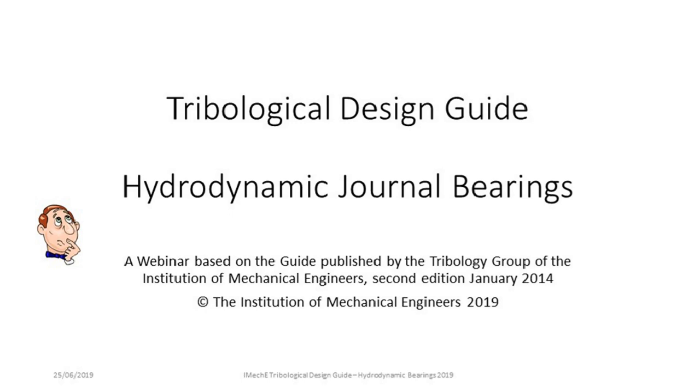Well, interestingly, with an electric motor, it's always a good idea to match the characteristics of the bearing to the characteristics of the device into which you're fitting the bearing. Now, the point about electric motors is they produce very high torque at very low speed, which is why they're attractive for vehicles, of course. But that means they're not very attractive for hydrodynamic bearings, because hydrodynamic bearings have no load capacity at zero speed. So electric motors tend to use rolling element bearings, and transmissions invariably use rolling element bearings.